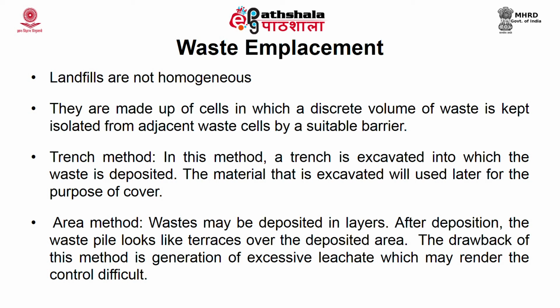There you can find a lot of compression, the initial compression, primary compression, secondary compression, everything will take place and the area will form a depression, which will act as an impoundment for storing water. So, it is difficult to control in the area method of waste emplacement.